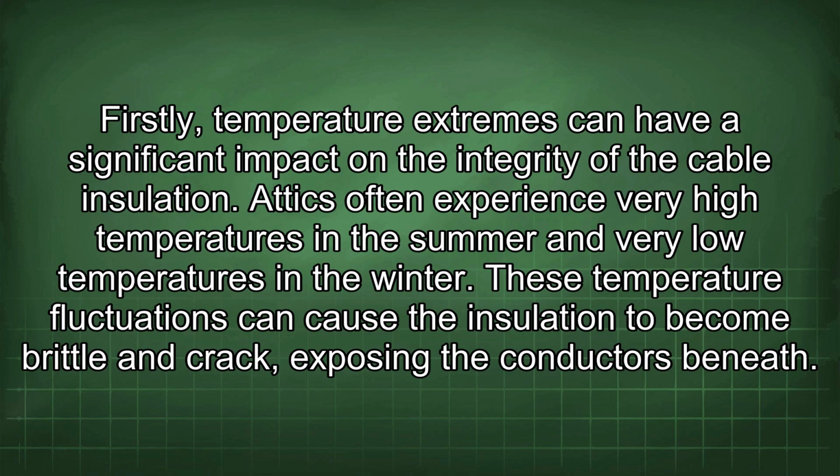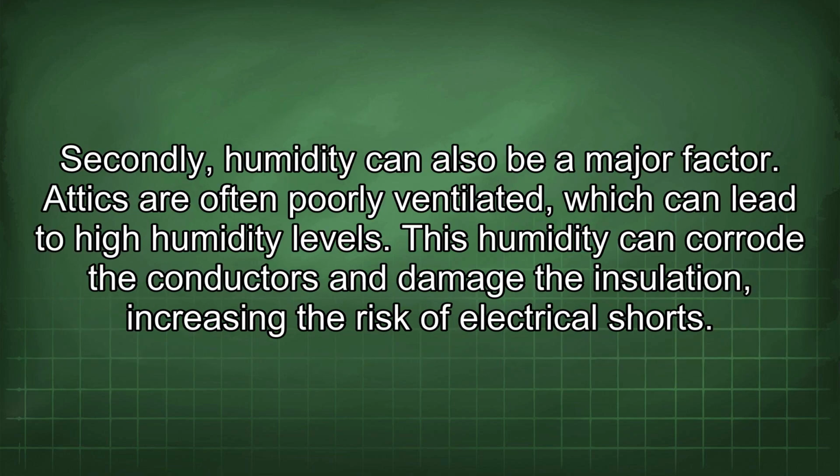Attics often experience very high temperatures in the summer and very low temperatures in the winter. These temperature fluctuations can cause the insulation to become brittle and crack, exposing the conductors beneath. Secondly, humidity can also be a major factor. Attics are often poorly ventilated, which can lead to high humidity levels. This humidity can corrode the conductors and damage the insulation, increasing the risk of electrical shorts.